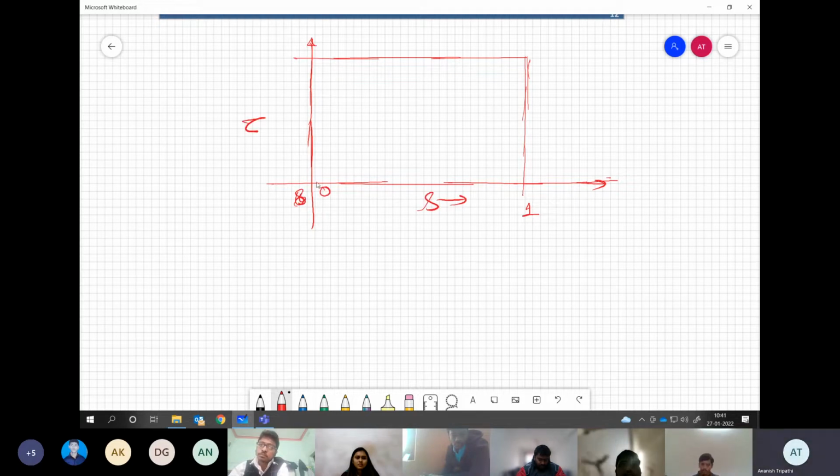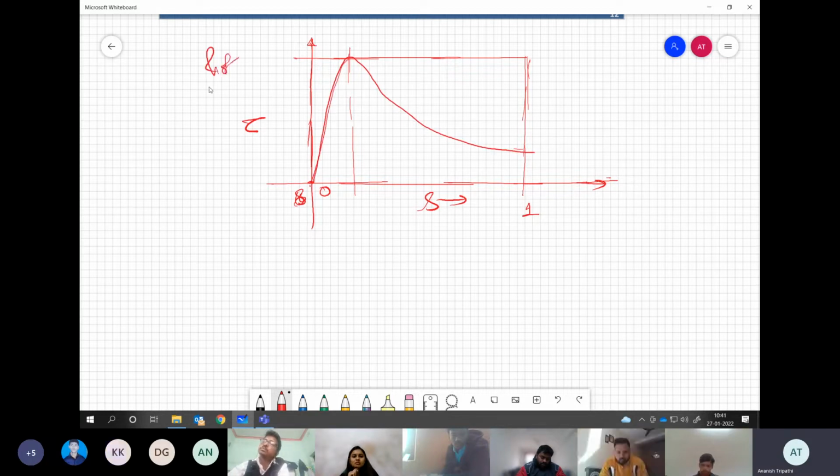If our characteristic is something like this, the actual characteristic, in the rotor resistance insertion method, what we are doing is shifting the point where the maximum torque occurs towards the high slip region, towards S equal to 1, and the best can be achieved at this point.